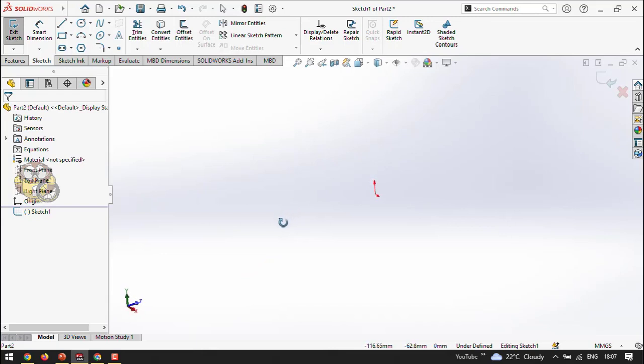Please see the axis at the bottom, X, Y, Z, the green, red and blue. It's rotating. See, these are the three axes. We call it a coordinate system. But in 2D, it is always two axes, X and Y; Z is not visible. We cannot create Z in a 2D drawing. Only in isometric or 3D are we going to use Z.